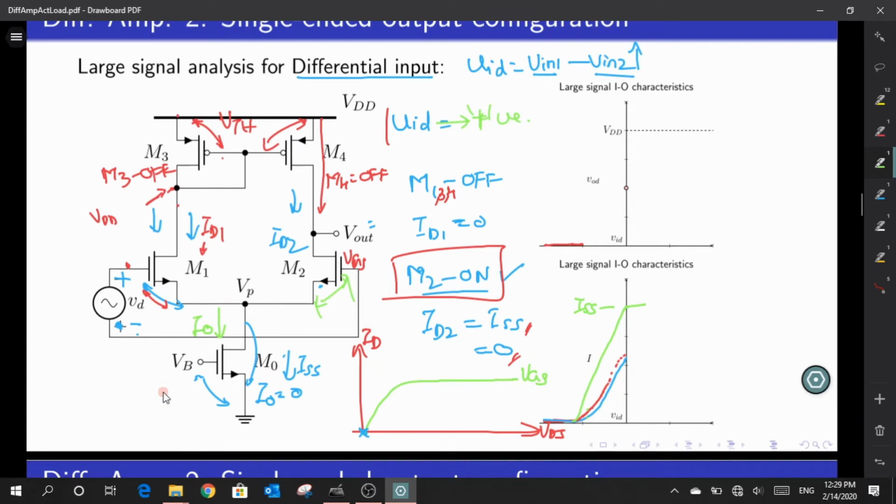So in that case, what would happen then? How will I reduce this current? You see, let me just go with the numbers, okay? So in this case, I have this 1.5 milliamperes, but the value of VGS that I have here is not capable of accepting this 1.5 milliamperes across the M2 transistor. So it is capable of accepting only 1 milliampere of current. Now, it's a mirror structure, but how can these things happen here?